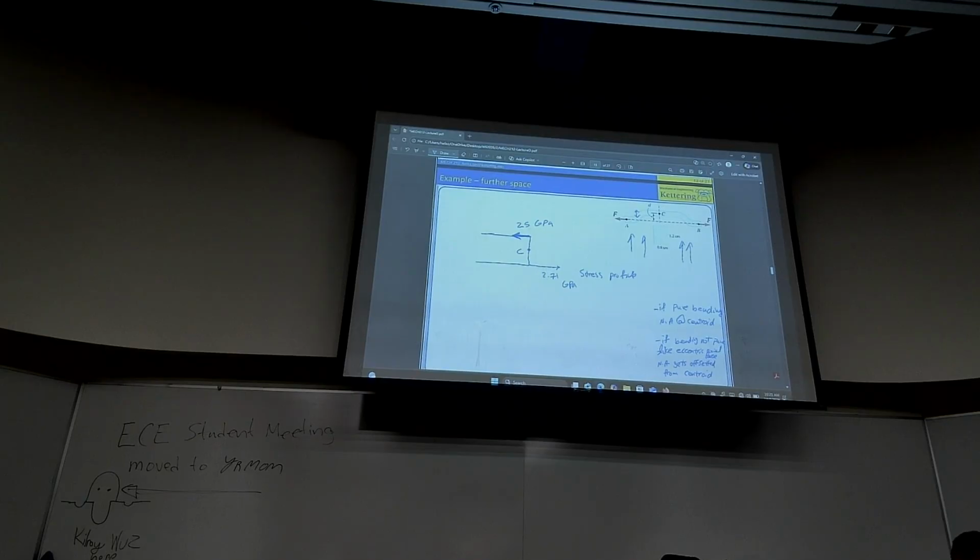So that means actually it shows up in here too. If I connect these two, if these two were equal, if we did not have offset, these would pass through C. But because these two are not equal and opposite, these do not pass through the centroid. There's a little bit of offset there. We want to calculate that. So this overall is 1.2 centimeters. I want to calculate this length.